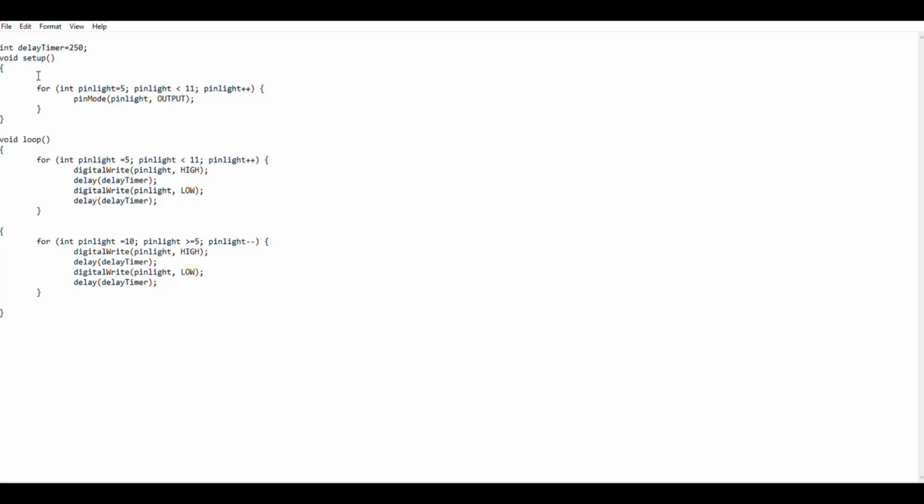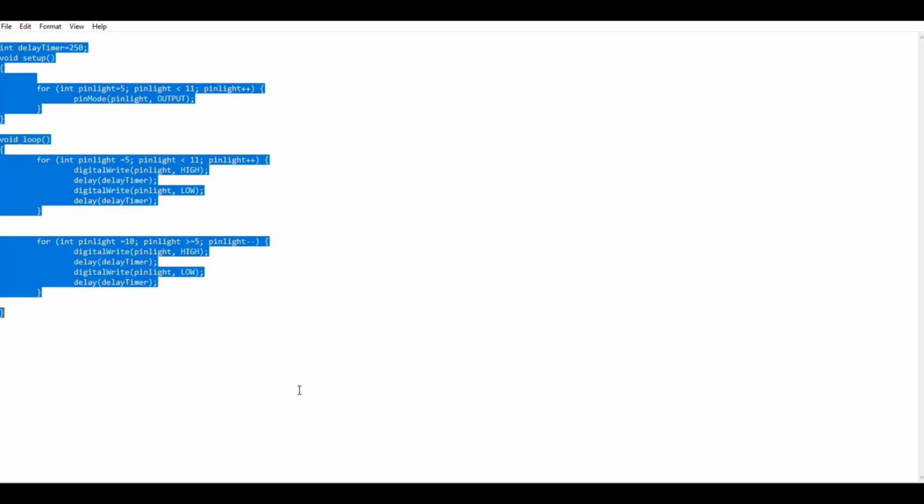That's totally okay. When you write coding, you make some mistakes. So it's always good to look inside the coding and make sure everything is okay. For example, when I copied and pasted, a curly bracket is extra, so I'm deleting that. And there are some semicolons missed. I have to add those, and now everything looks good. I'm going to copy this code and come back to the Arduino circuit for that project to run this and see if it works properly or not.